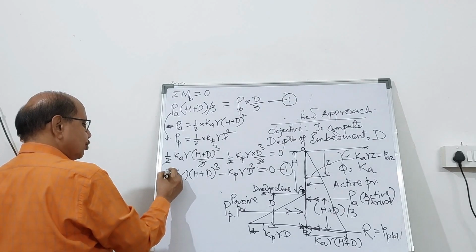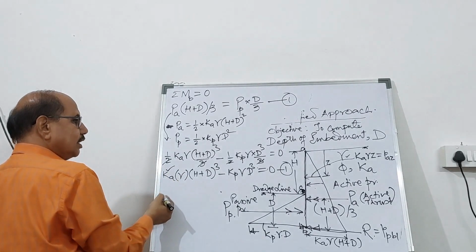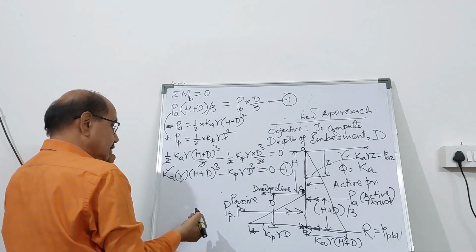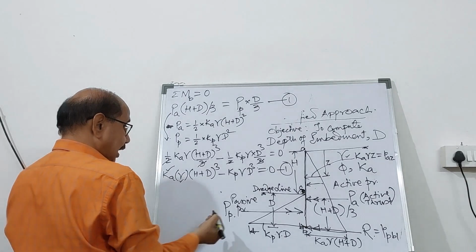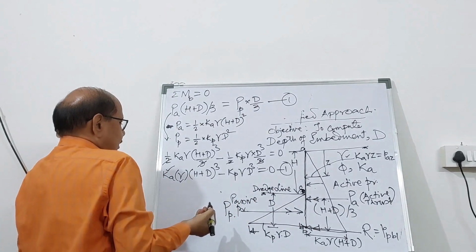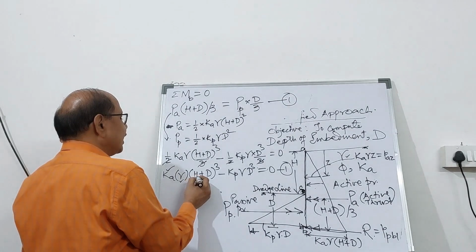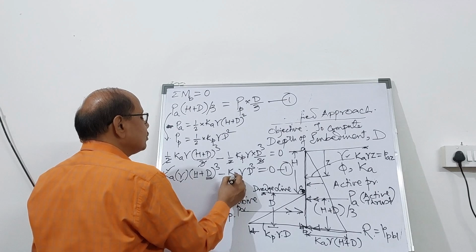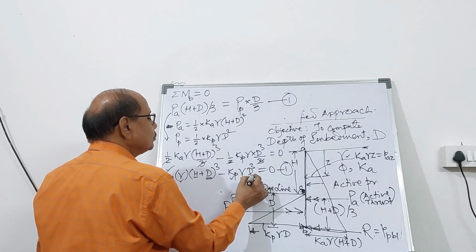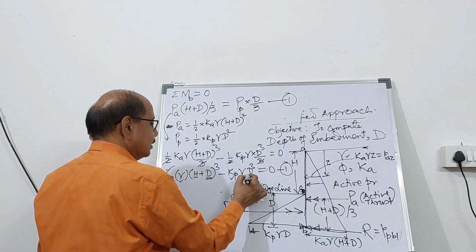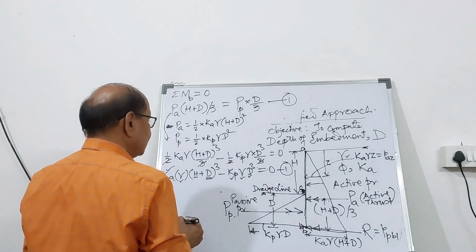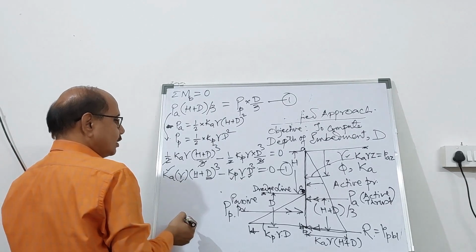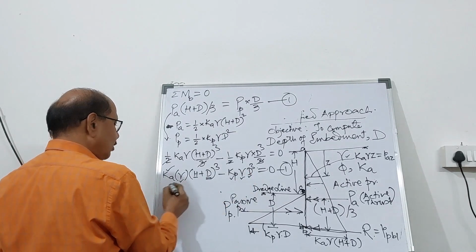So from this, K is known because the phi value is known, and therefore K is always known to you. Gamma is the ground property, the backfill property, and below the dredge line, gamma will be known to you. The height of the cantilever sheet pile is known to you. Kp is known to you, and the depth of embedment we want to find out. So you get a cubical equation, and therefore if you solve it,